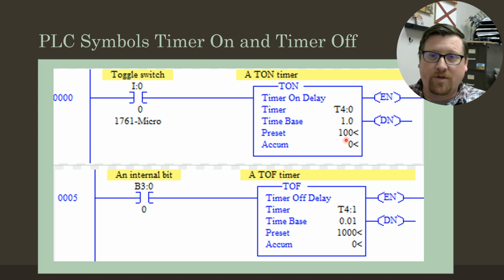If you're counting 1 second at a time, that's going to be hours. But if you're counting in hundredths of a second, you're going to get to 32,000 in minutes, not in hours. And some of the newer ones, the 5,000s, you can actually go down to thousandths of a second, and then you're talking about only like a 30-second timer.